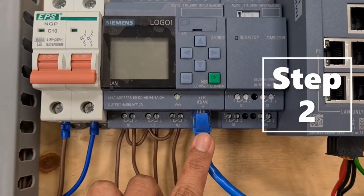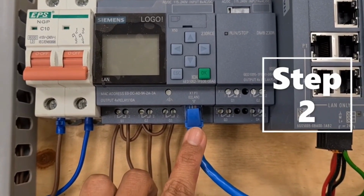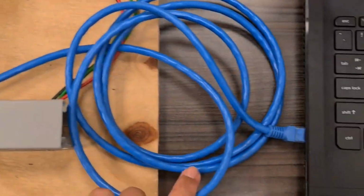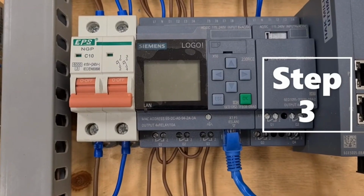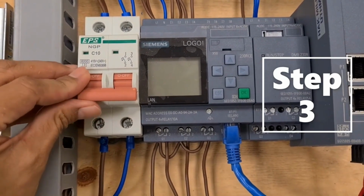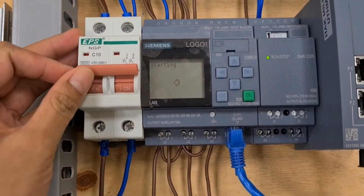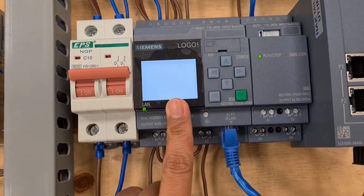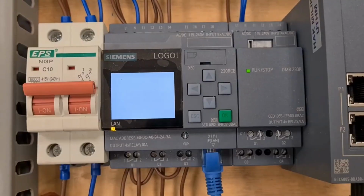Second step, connect your PLC to the laptop using the Ethernet cable. Third step, turn on your PLC by pushing the main switch up. Once it is turned on, you will see the date and time on the PLC screen.